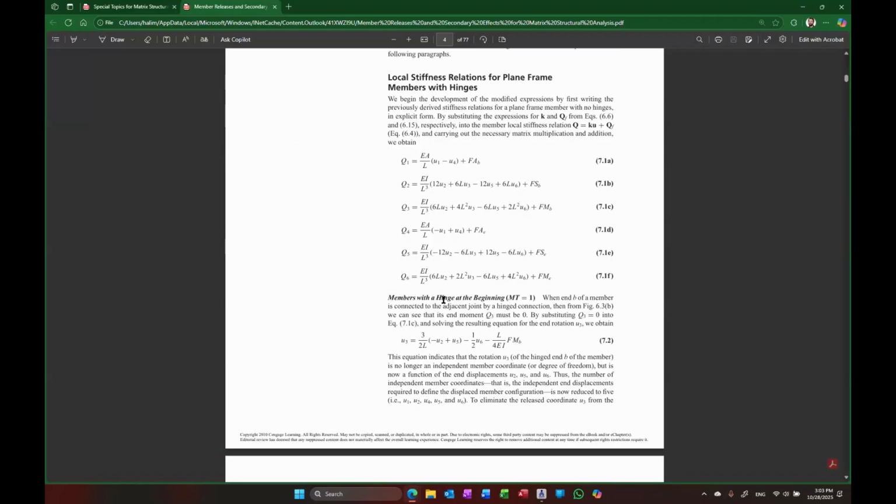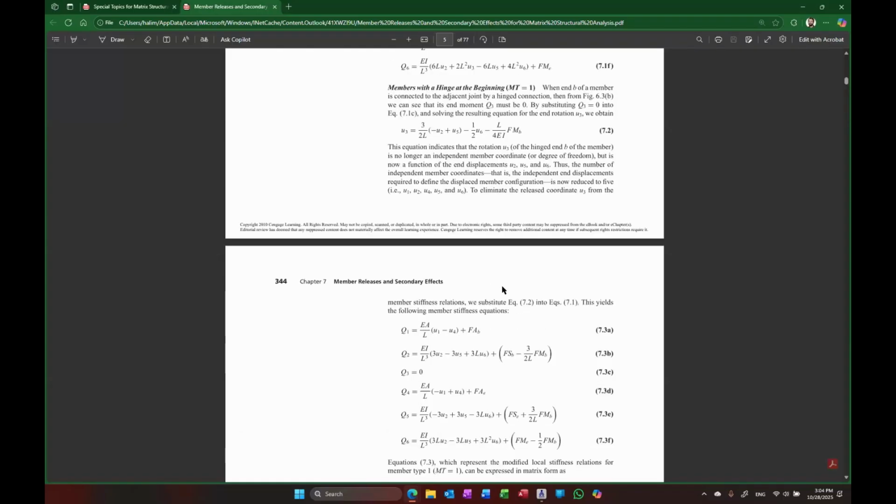I don't know if you probably came to this point by creating your own element matrices and structure matrices, etc. But if you don't do anything additional, obviously the conventional regular element matrices, when they come together, they all simulate perfectly joined, fixed joints between each element. So we have to do additional work to simulate hinges.